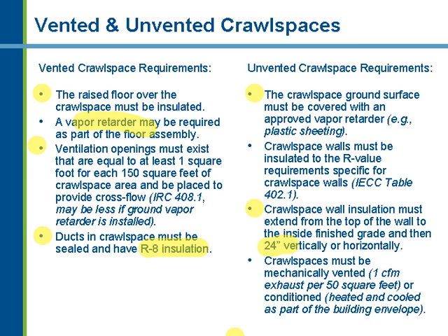There is no requirement for your typical crawl space ventilation in this case, but there is a requirement that you either provide a little bit of conditioned air into that space or some mechanical ventilation through that space just to keep the air moving very slightly. And you can see the values in the code for that.